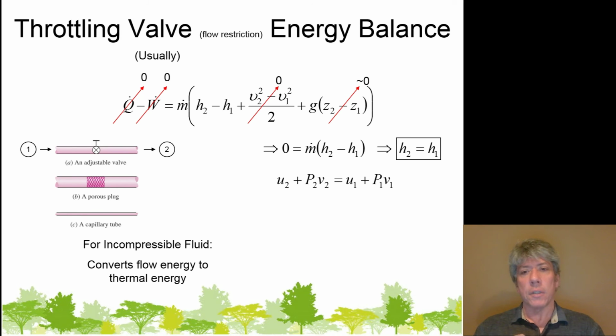and continue the cycle. So in the case of an incompressible fluid that does not boil off, all this does is convert between flow and thermal energy. As a matter of fact, that's all it does in any case, is convert between flow and thermal energy. For compressible substances that will change phase, this could be a different story. Depending on the nature of the fluid, the temperature may go up, or it may go down, or it may even stay the same. It just depends. You've got to select the right fluid for the particular application.